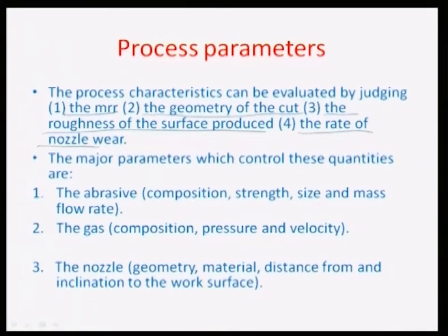So, any good machining process would typically need a lower wear rate, thereby meaning that the nozzle has a better working life. It should be able to produce low roughness surfaces, and you should be able to do complicated geometries in terms of machining, and the MRR should be high yield, meaning thereby the MRR should be higher.